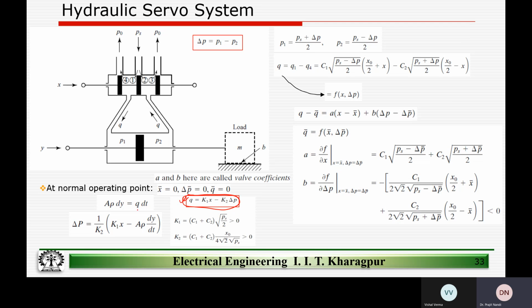So I replace this in this equation, and I rearrange the expression in terms of delta P, right? So now I have done a good thing. I have got hold of all the knobs that I have, X and Y, which are easy to measure in terms of movement, and I have been able to use these independent variables to express the pressure differential created across this chamber, right?